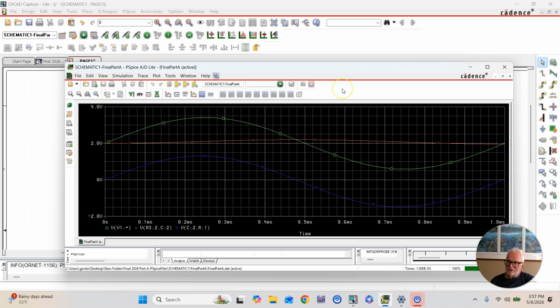You decrease the denominator by a factor of 10. Your X of C, 1 over 2 pi f c, is going to rise by a factor of 10. So the capacitor is no longer approximated at a 1 kilohertz frequency as a short. So I don't think of it that way. I hope that makes sense.